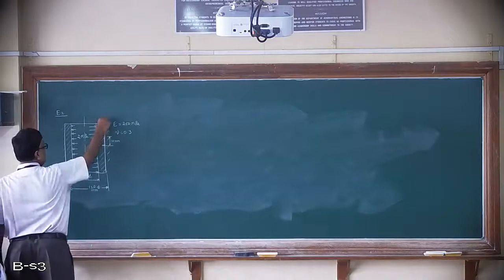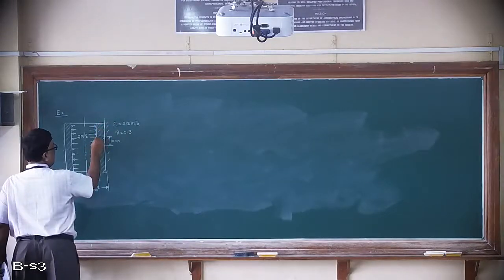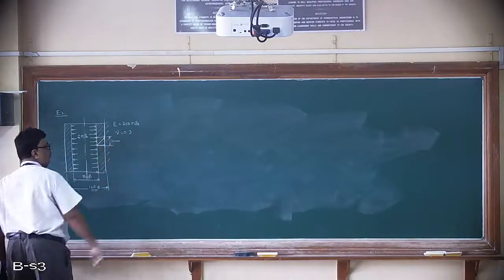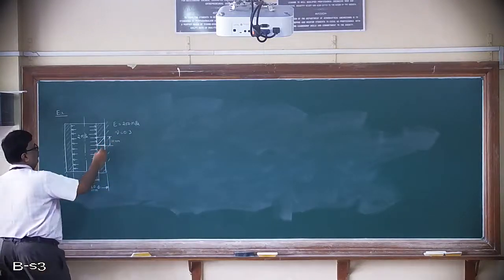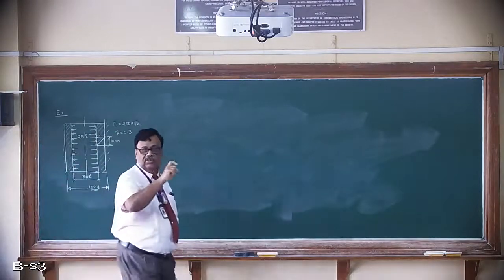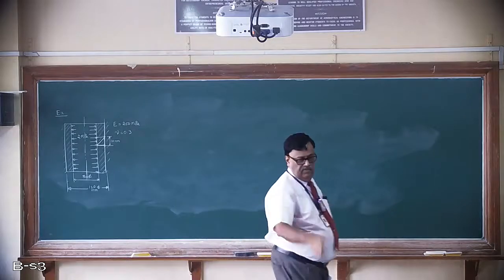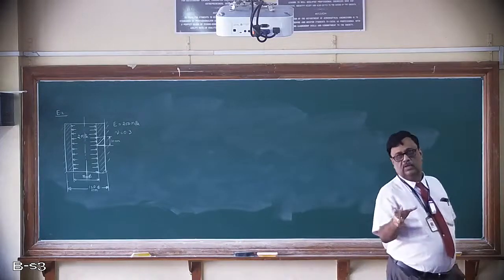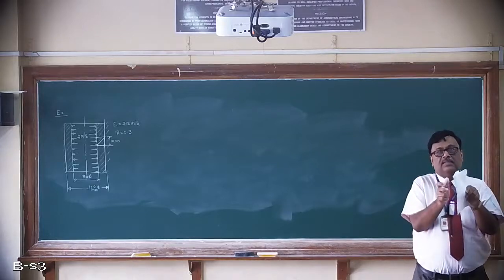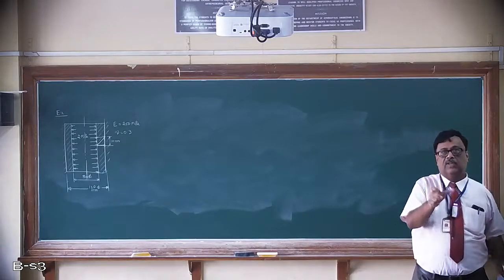Since this edge is completely fixed, only these two nodes can go inside. These are literally fixed from moving outside. If you look at the boundary conditions, these two nodes are literally fixed because the wall is snug fit inside a hole. So therefore, no question of expansion of the outer cylinder. Only the inner cylinder can expand because of the pressure which is there.